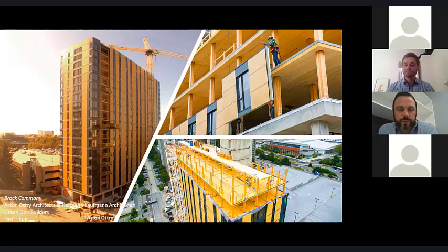So just spend a bit of time, I say a bit of time, but a few more seconds, just really observing this image, because we do bring this up on a number of occasions during the presentation. The important things to note are how it's going away from that shear wall or honeycomb style structure. You're mainly dealing with posts, and this is more of a flat plate, no beam approach. The other thing to note too is the loading bins at each level at only one bay location. So just note those, and we'll reference that a bit further in what the challenges are with a traditional, more honeycomb style structure from a buildability and logistics perspective.